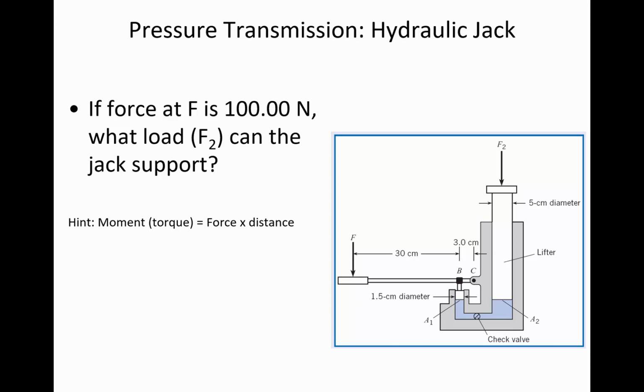And so when we go through the calculations here, what we're going to see is, first of all, the first way that the force is being amplified is the longer the lever, the more you're going to be able to crank down at location B. And this is the same idea if you are trying to get the wheels off of a car. If you have a really long handle on the wrench that you're using, if you're using a breaker bar, they're sometimes really comically long. What you're trying to do is cause a really large force. And so we're amplifying the force.